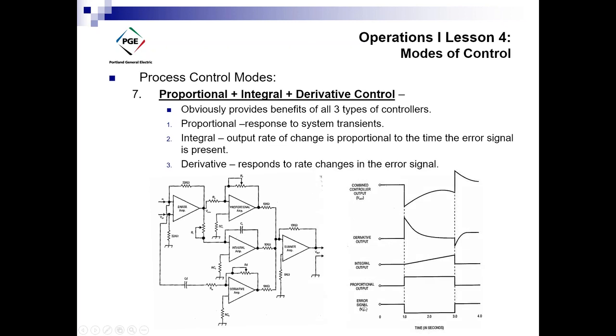And so this graph will show it. So let's say you have, the reference is negative, so you have a negative error, constant, and then it goes away. So your proportional output will go in the positive direction, which is inverting, so it wants to overcome the negative error, and bring it back positive. Same magnitude. So it just looks the same except it's the opposite.